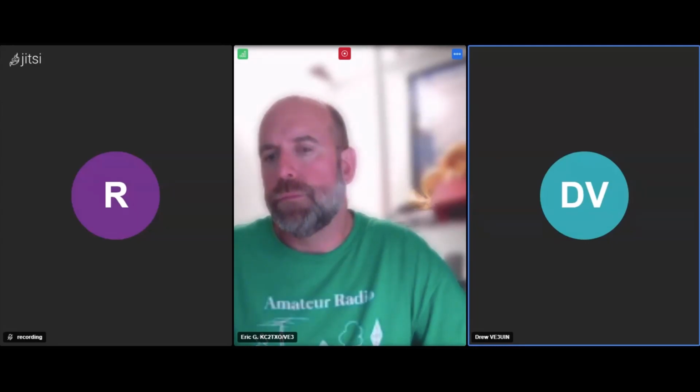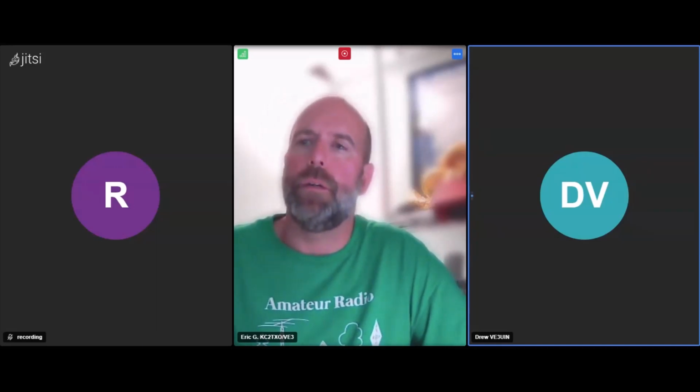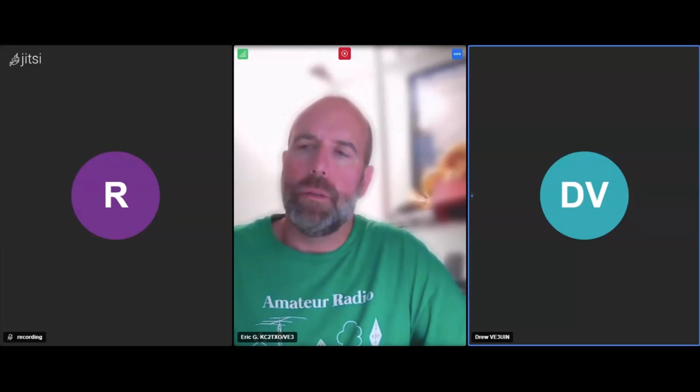coax. So you have this wire going along the bottom to form the bottom of the triangle. Right. And that's connecting the ground to the ground. And then the antenna section is in a big delta configuration. Right. And essentially what you've got is a 450 ohm dummy load, but it has a radiating wire in it. They're not terribly efficient, but they match 1.8-30 easily.